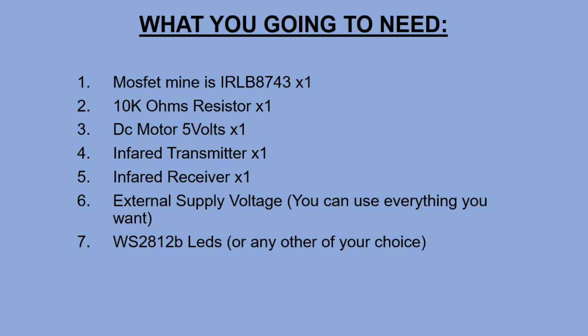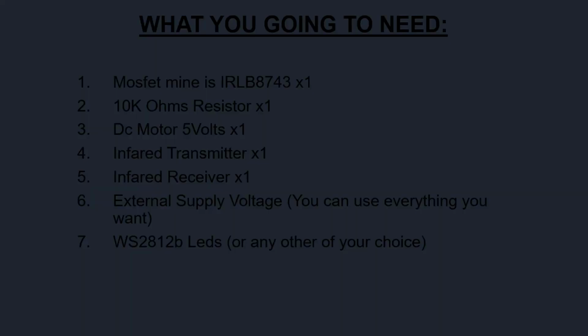You are also going to need a LED strip of addressable LEDs, such as WS2812b. You can use as many as you want, but keep in mind to declare the number of them in the code, and supply them with external voltage, because as you know they consume a lot of energy. At last, we are going to need a microcontroller. You can use whatever type of Arduino microcontroller you want.